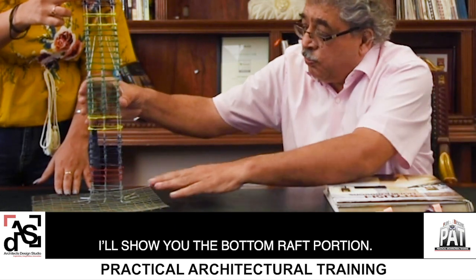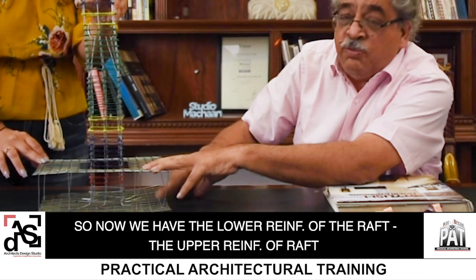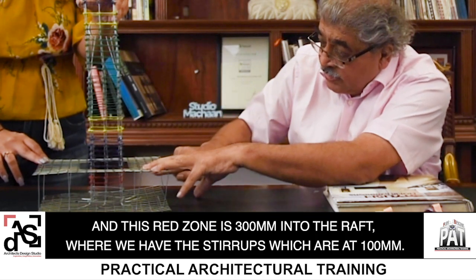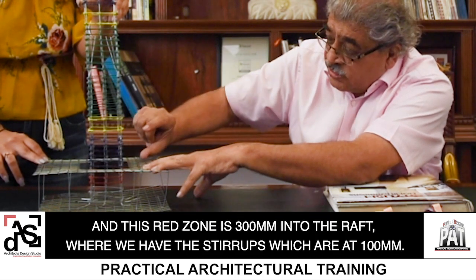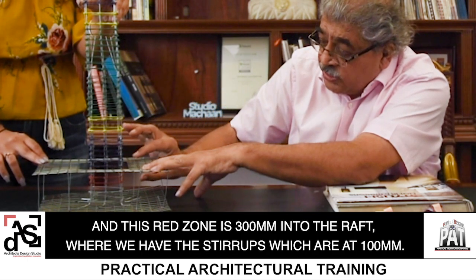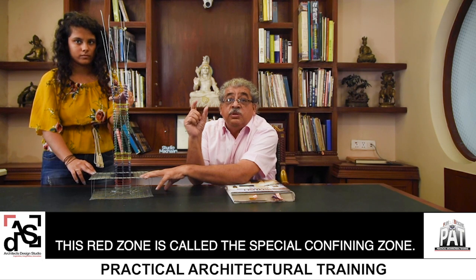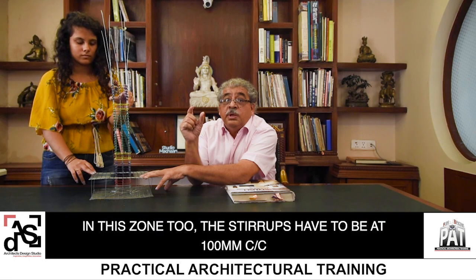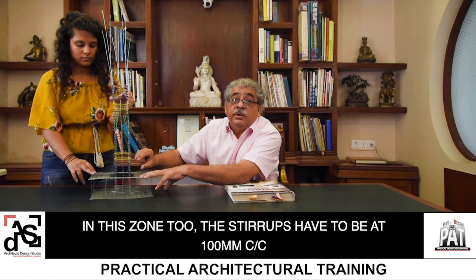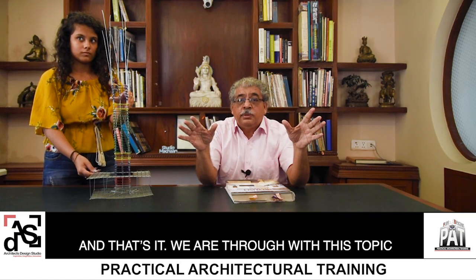So I'll show you the bottom raft portion also. So now we have the lower reinforcement of the raft, the upper reinforcement of the raft, and this red zone is 300 mm into the raft where we have the stirrups which are at 100 mm. This red zone is called the confining zone, special confining zone. In this zone too, the stirrups have to be at 100 center to center. And that's it. We are through with this topic.